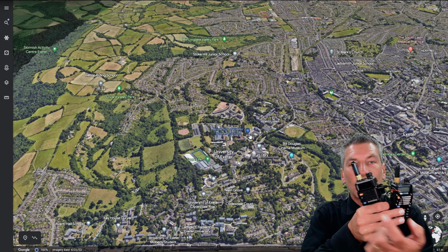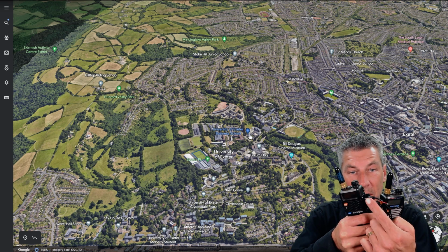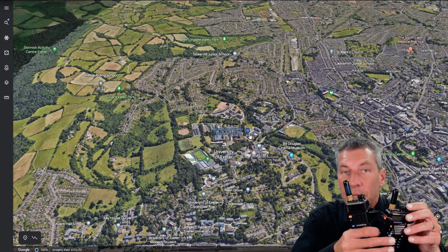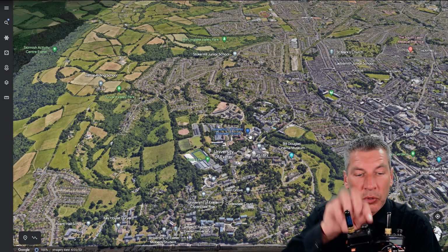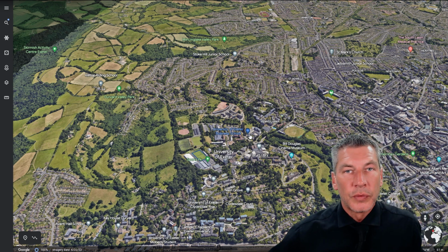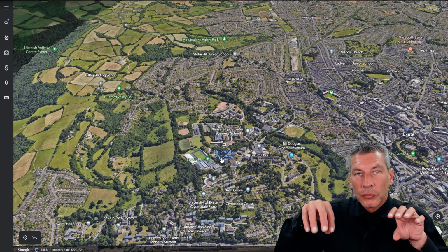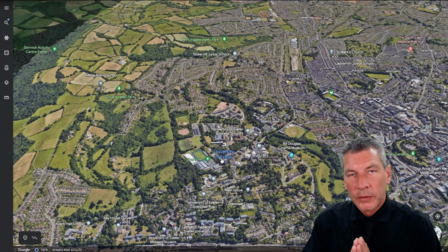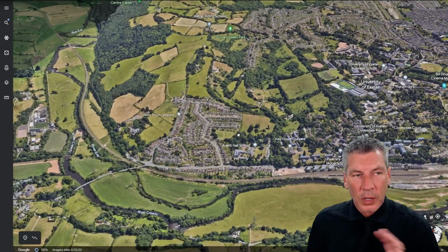So you talk to this one with your ham radio, and it goes straight into this one. The speaker out here goes into the microphone in here, and this one transmits out at the same time at a different frequency. So it comes in here from you, and it beams it out of here. Exactly what you're saying goes in here and back out on a different frequency. So the idea is you have a different frequency for transmit and receive, and it allows you to transmit and bounce your signal through a relay. The other benefit with that is you can use more directional antennas with your ham radio for these long distances that we're talking about now, for our security for a wider area.